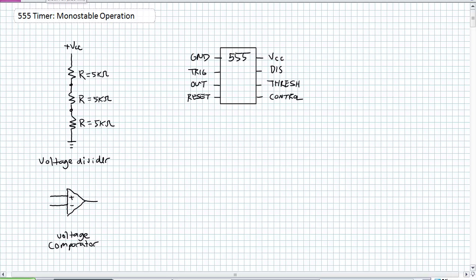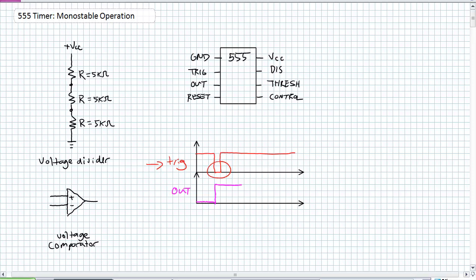So what a timing diagram for a monostable one-shot would look like is something like this. Let's assume this is an active low trigger device, and what we've got is our trigger input right here, and at such and such a time it has an active low pulse. So what's happening is our output was a 0. That is its stable state. That's the monostable state. Once it's triggered, it can go to its opposite state for a predetermined period of time, which I'm going to call TW, the pulse width, at which point it will revert back to its original state. And let's say another active low trigger occurs right there. What's going to happen? It's going to go ahead and assume that opposite state for that exact pulse width.